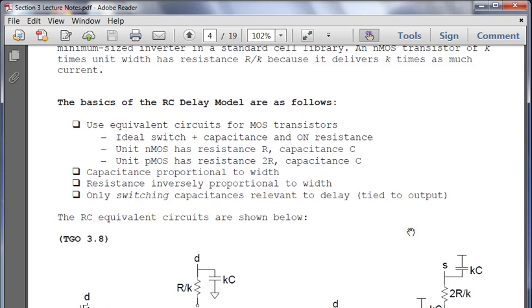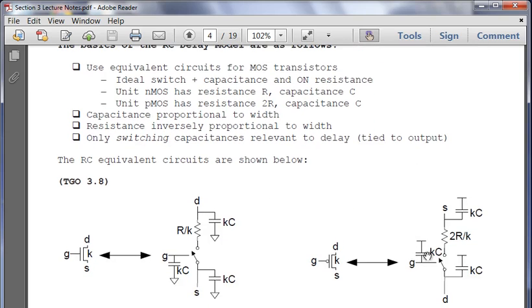Additionally, for PMOS, we have our source and drain. We have a capacitance KC, so it's initially going to be 2, right? So it's 2 here, so that's going to cancel out, and we're going to see how the resistance is going to maintain the same resistance throughout the inverter. So we want to cut in half. So if the resistance for both the PMOS and the NMOS is the same, that's when your beta ratios are going to be the same, and that's when you're having proper circuit operation.